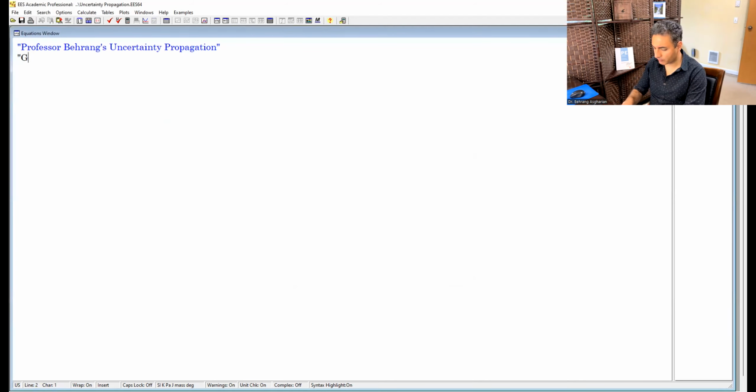Now, the first part is you just have to type in the values that are given. So the pressure was given as 100 kPa, but I will have to convert this to Pascal. So I've got to go from kPa to Pascal. I do that. All right, cool. And the next step is temperature. Temperature has to be Kelvin, so I've got to use the convert temp function and go from Celsius to Kelvin. And the temperature was given as 200 degrees Celsius. That's pretty much it. If I want to use the ideal gas law by hand, I'm going to enter the value of R as 287 joules per kilogram Kelvin also. Okay, cool. That's pretty much it.